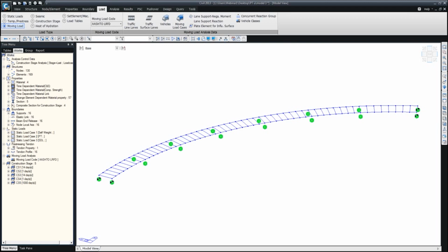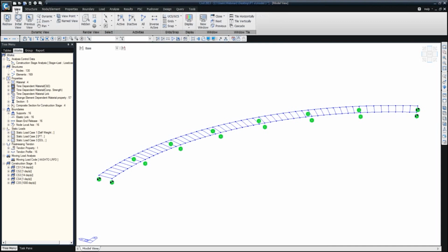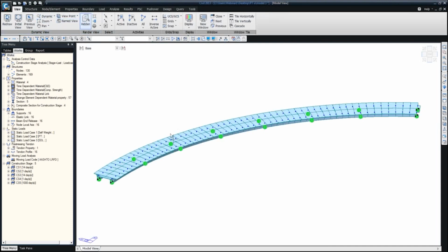It is just to replicate the transverse stiffness of the deck. So when we are saying we have the lid slab and the deck slab in the picture, we are saying that their longitudinal stiffness is taken care of, and the transverse stiffness of the deck is being represented by a transverse member.